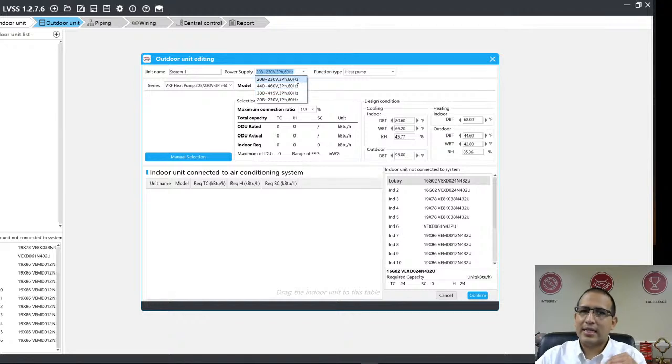Because at the beginning we selected standard 60 Hertz, I'm getting only the 60 Hertz items. However, because our product is fully inverter, even if it's rated at 60 Hertz, it's also compatible in 50 Hertz. So it doesn't really matter your market. For our products, we still have the air handler, the vertical air handlers, and the high walls that are still either 50 or 60. However, we do have a new generation of the high wall that are fully inverter, which is a DC motor, and the air handler on the certified product is also dual cycle, dual 50 and 60. So you can choose those as your options.